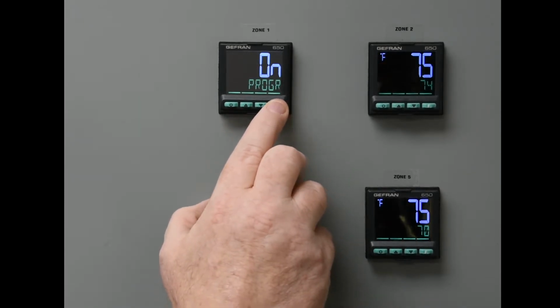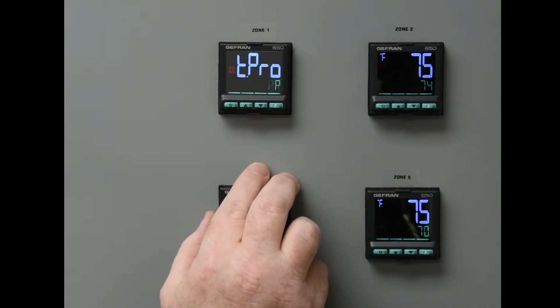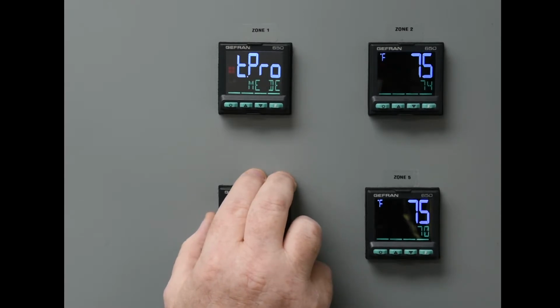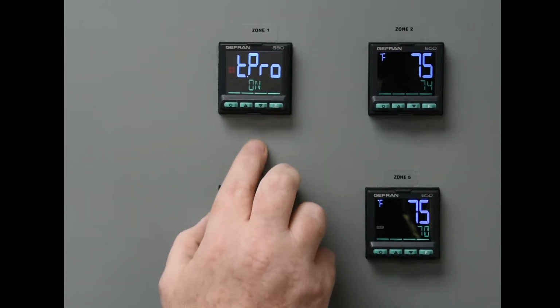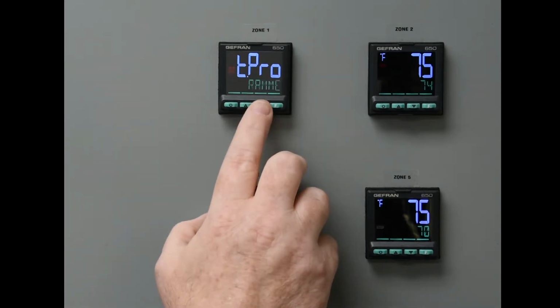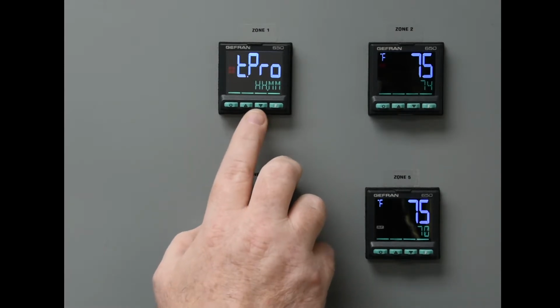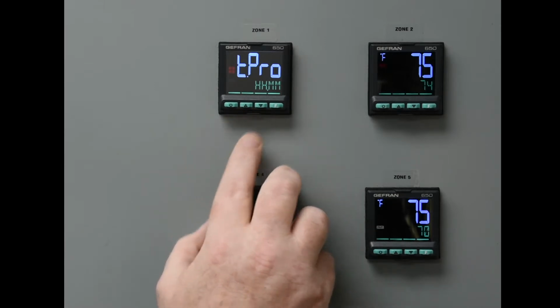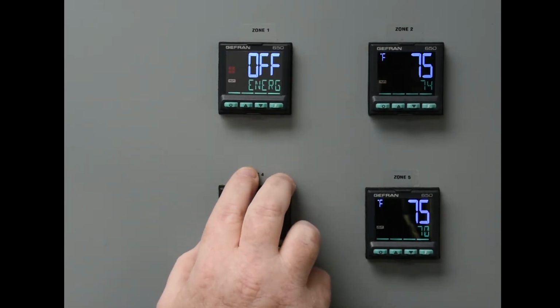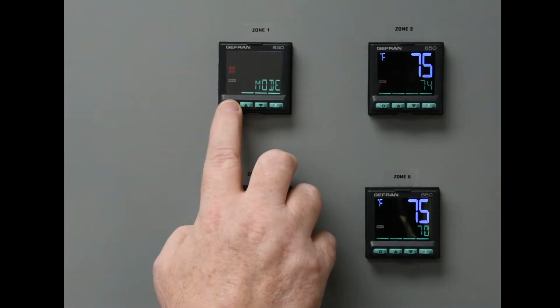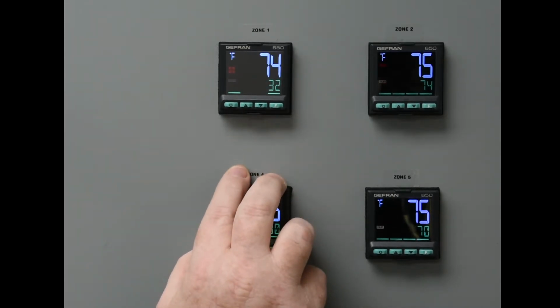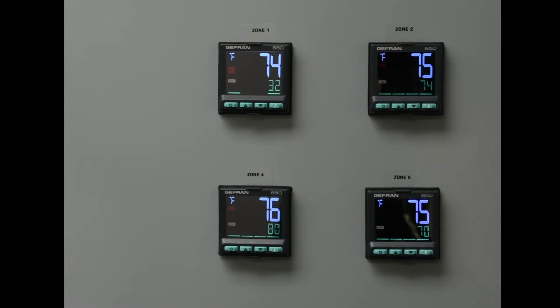Press and release the F key until T.PRO for programmer-based time definition is on the screen. This shows the programming time parameters. HH.MM is the default for hours and minutes. Use arrow keys to change or press and release the F key to accept. Press and hold the work mode key on the far left until the display shows temperatures. Your controller is now in the programming mode and you can create a program.